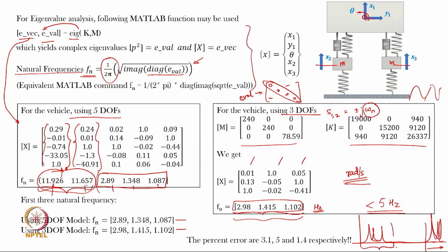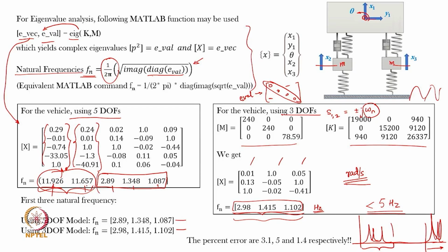So, most of your first few natural frequencies are of course going to correspond to the numeric values which we have chosen in this particular vehicle model, but trust us that these values are not imaginary. The values taken are realistic values of a typical motorbike, taken from some source. So, these are realistic values of the tire and the chassis, and also the suspension stiffnesses.